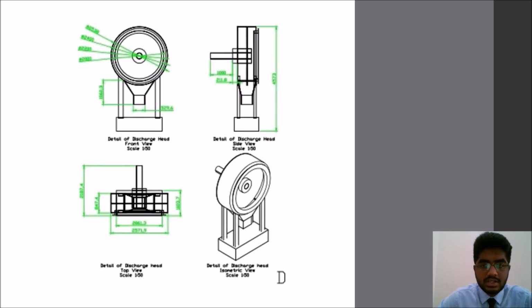This will be our discharge head, where product exits the dryer. This section is where the drying air is directed through the drum from the combustion chamber. This will be our air seal, which connects the discharge head to the rotating drum in order to keep air and material from prematurely exiting the drum.